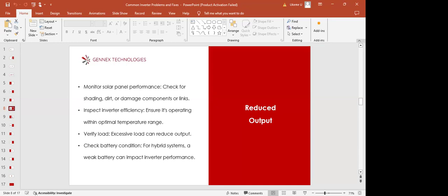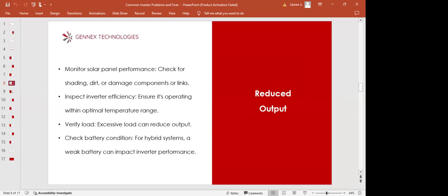Now, where that comes to play is, for instance, you have a batteryless system. The way batteryless inverters behave, when the solar power is going down because of generation, the output voltage too will be going down within a range. If you discover that instead of 230 you are now having 200, it may not shut down at that time. But because it's batteryless, there is no reserve for it to just peek from.